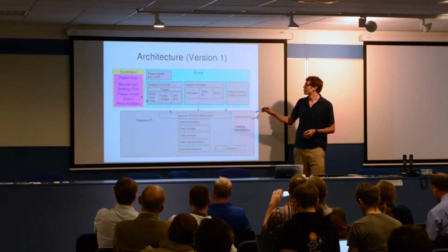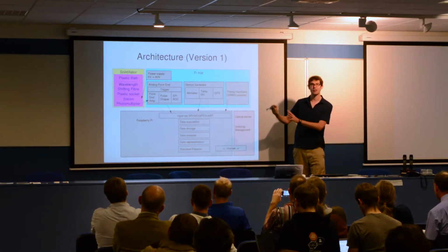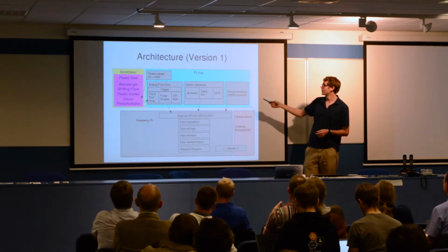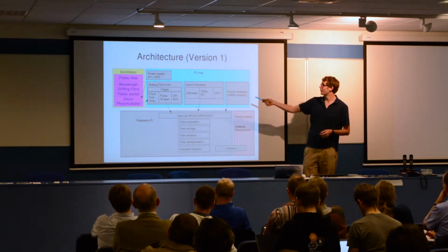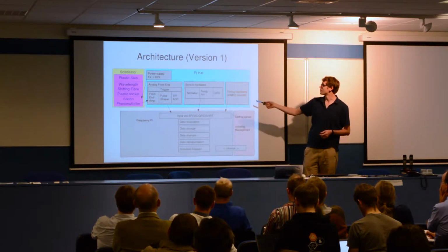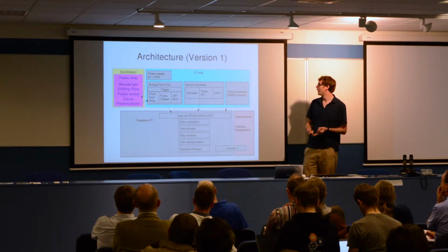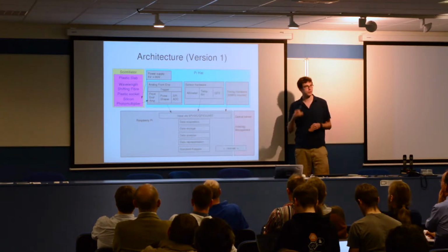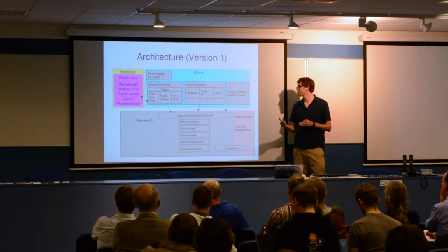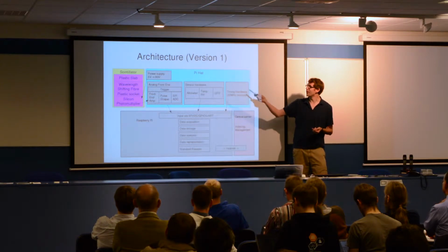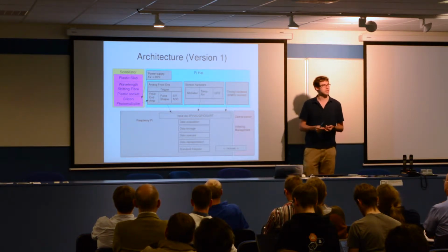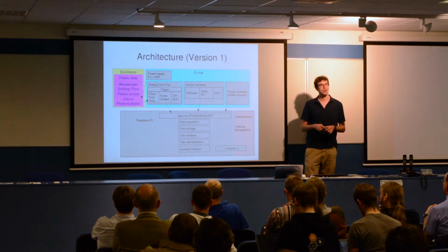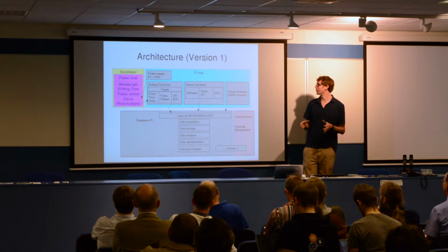In terms of the structure, we have the plastic slab, the scintillator package effectively, that's the mechanical part. Then on our Pi hat, we put a high voltage power supply, the analog front end, and some sensor hardware: an altimeter, temperature and relative humidity, and a GPS. The altimeter is there because we can't get good altitude resolution from the GPS. The temperature is there because it affects the performance of the silicon photomultiplier and the power supply. The relative humidity is there because relative humidity attacks the plastic scintillator. So over time, if it's in a high relative humidity environment, its performance will degrade.